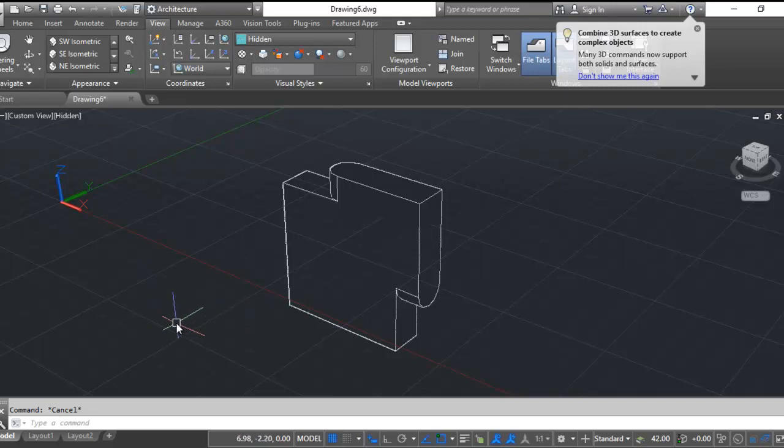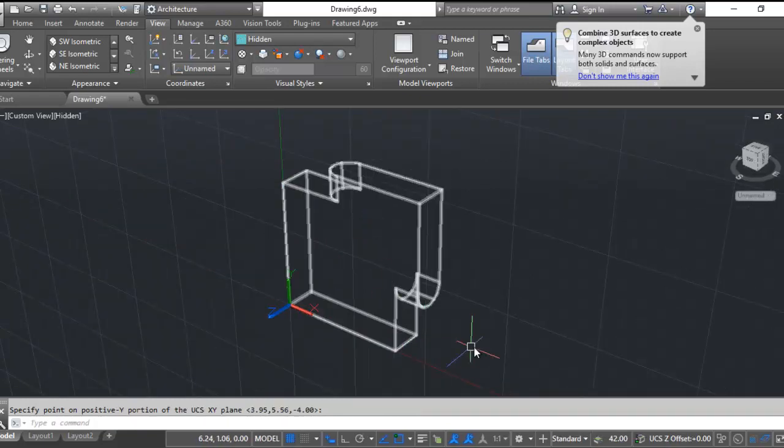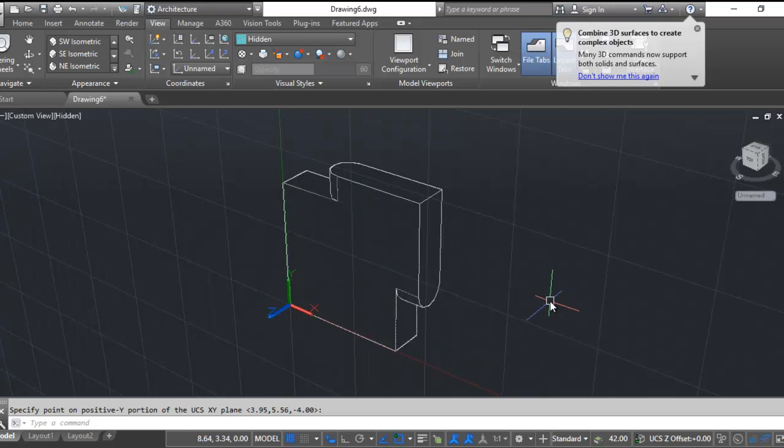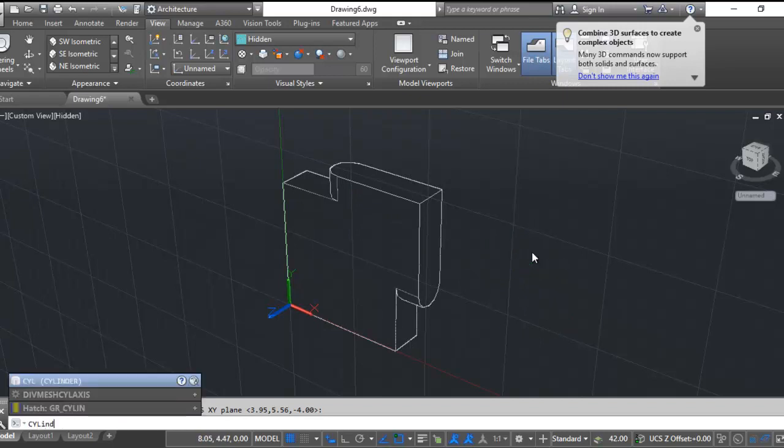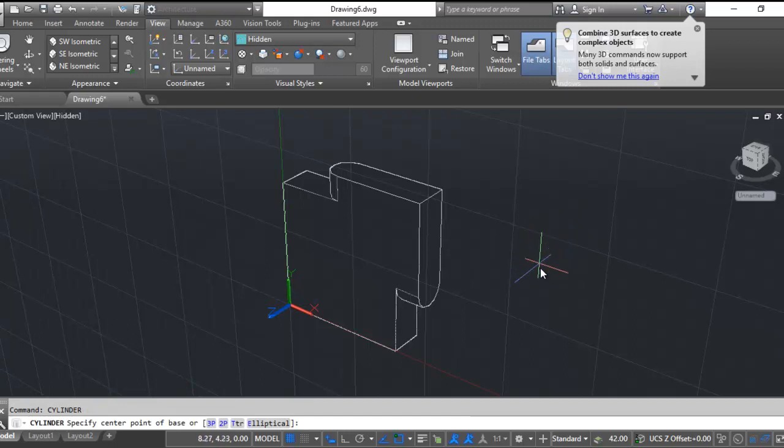So to make the through hole, we'll do the face first. We should have our UCS in that orientation. So if I do UCS 3P, enter, pick the origin, pick the X, and pick the Y. Now I'm on this plane, which is helpful. And I'm going to give myself that cylinder. So this is where I told you, hey, you can change your UCS and then draw, and you don't have to rotate it. So cylinder, and I'm going to this time draw it based on the corner.